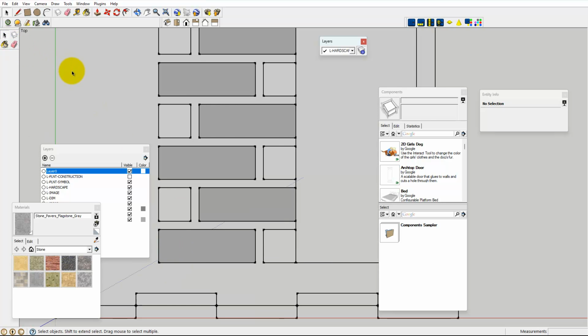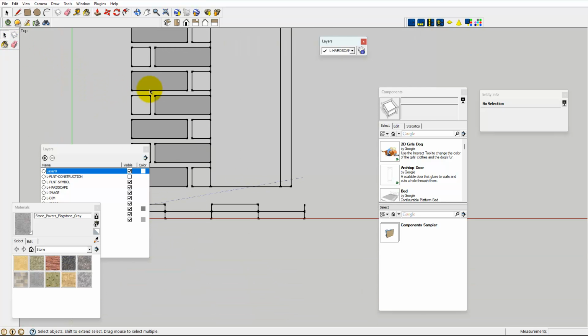So can you see how easy it is? Let me zoom out a little. In 3 or 4 clicks, we've taken what was in gCADPlus and brought it across into this environment. Now, that's nice. It's easy and works extremely well. The downside is that you have to have some sort of plug-in or get SketchUp Pro, which allows you to bring in this sort of information.